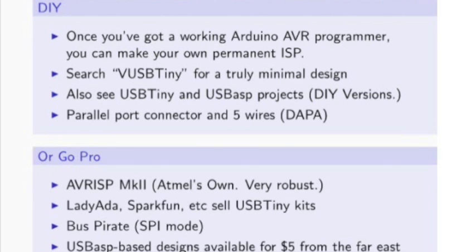And finally, I should say this in good conscience, there's a bunch of really cheap knockoffs of the USB ASP design, mostly from China. Some of these are a little bit electrically fragile in the sense that they have power limiting resistors on their outputs that make the digital logic voltage, especially if you're using long cables, which they do for some reason, a little bit sketchy. You can remove these resistors, but at that point, you might as well make yourself a solid DIY design or pay $20 and get something a little better, in my opinion. On the other hand, they work.